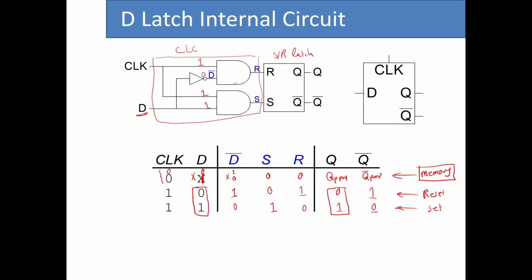So that means that in the design of the D-Latch, whenever clock is 1, whatever value we have for D is going to be seen in Q. And that is what we called being transparent, right? We said that when clock is 1, the D-Latch is transparent to the changes in data. So that is basically the transparency.